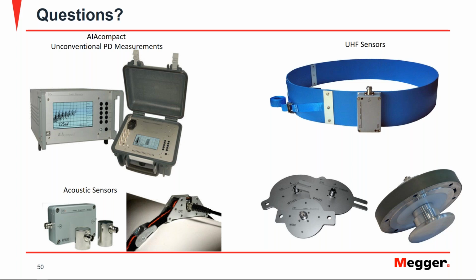With the electrical method, you do have, with really sophisticated equipment, the option to go for a time of flight measurement, but the electrical signals are way quicker. So you will get a less detailed and precise location of your measurement. The acoustic signals are slower, and accordingly, it's easier to identify the location of PD. So first, electrical for identifying if there is PD, and then acoustic for identifying where that source of your signal is located.